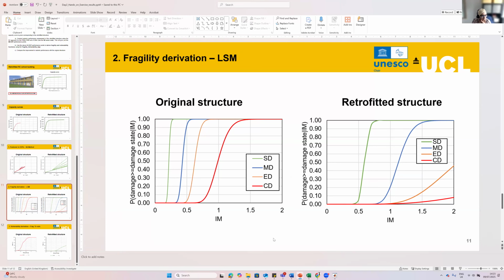So, could you explain how you selected the ground motions and used the worksheet? These ground motions are basically selected from the far-field ground motions in the FEMA guidelines. You can use any set of ground motions. You can select them based on certain parameters that are relevant for your region.